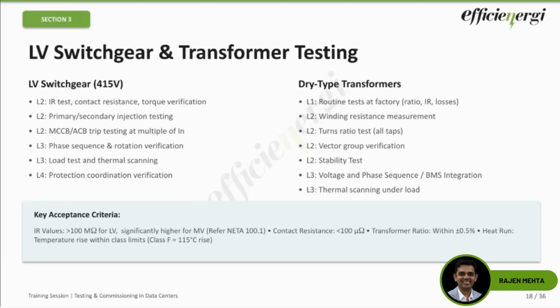From your documentation point of view, it is important that we capture the baseline. This is the stage where you get the opportunity to capture your baseline readings during the commissioning. So it will become a reference during future maintenance for the customer, right? So doing it properly, documenting it properly, ensuring the tests are done properly allows proper trending over time, and it provides degradation trends for the customer.